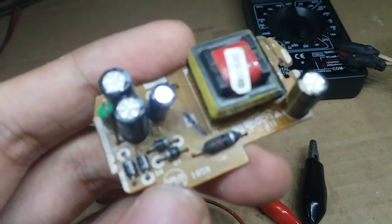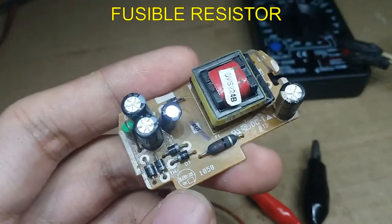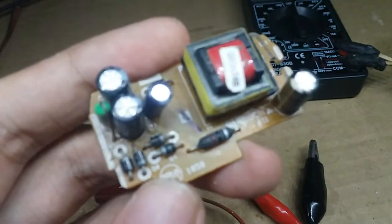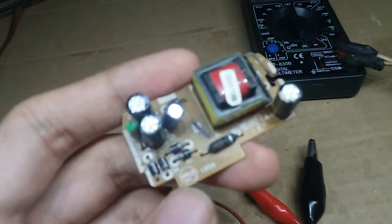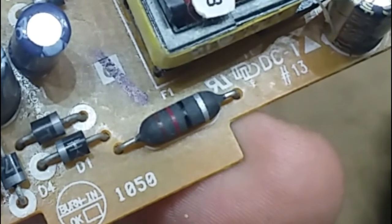There's also another type of resistor, which is called a fusible resistor. As the name implies, it acts like a fuse. When something happens in a circuit, they will not burn and cause fire. Instead, they just fail open circuit because it's somewhat made of ceramic.